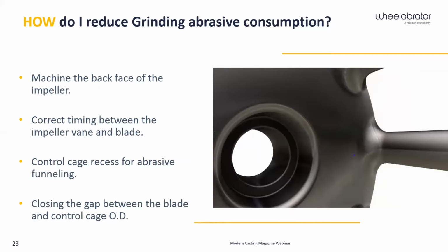And, in the old days, a lot of those impellers, when they seated inside that control cage and used your impeller bolt to bolt it in, they would lope. And maintenance personnel, operators, whoever was changing it out, they would put shims in these things. They would pull them out, move it 20 degrees, try to put it back in there. And you just kept putting it in there to where it loped, but it didn't actually hit the control cage. If you couldn't hear it, that was good enough, and everybody went on.